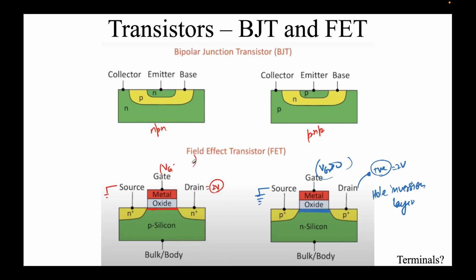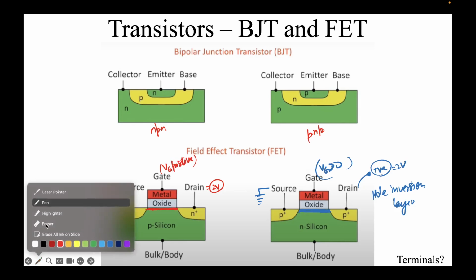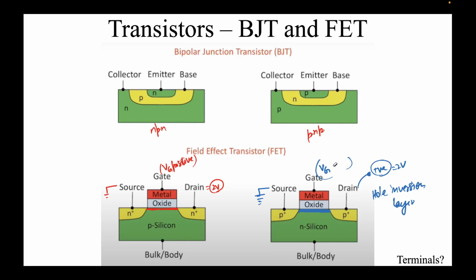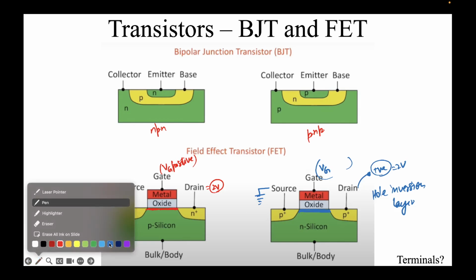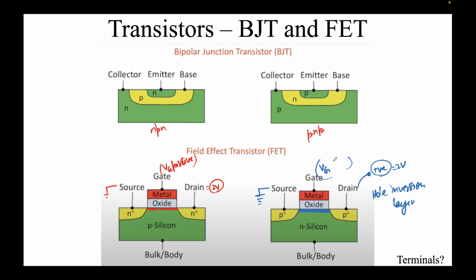Vg is positive because we are talking about the p-type silicon. So in order to form an inversion layer, the holes have to be repelled. Similarly, on the other side here, the Vg has to be negative, not positive. So Vg has to be negative.